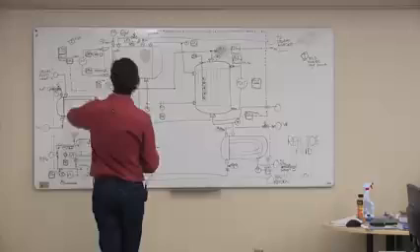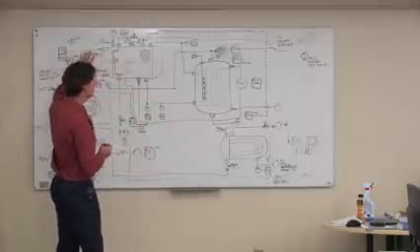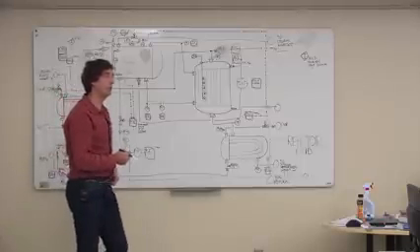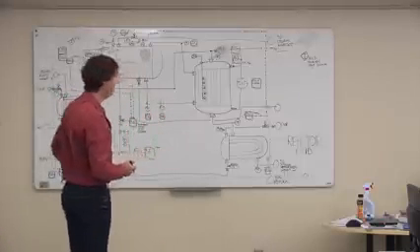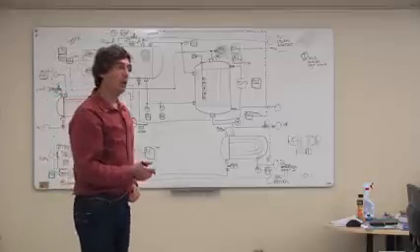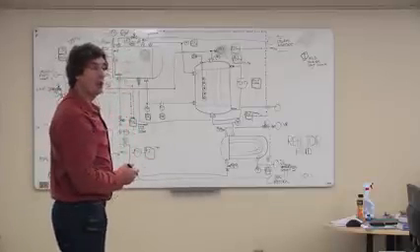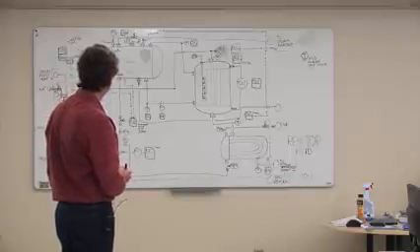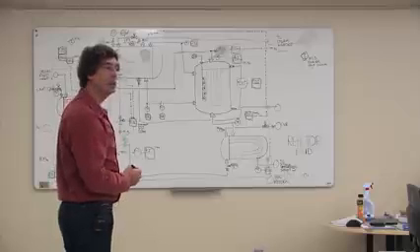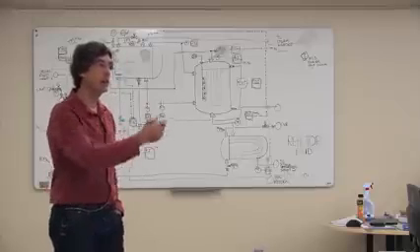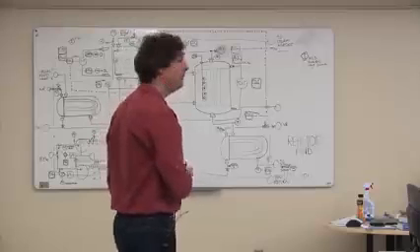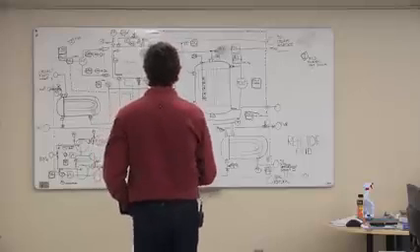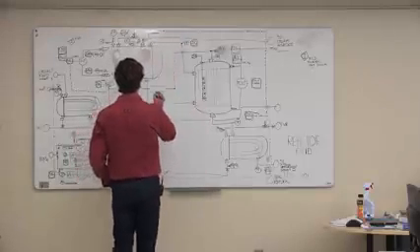Just a basic level gauge. Well, the level's here, right? So yeah, you could drain a little bit off, except that the level would probably refill as fast as you can drain it out of there. Can we not see it through the glass? You see the solids, you mean, or see the level? You might see the solids. I doubt you'd see the solids because you really don't want to have that many solids in there. You could be measuring conductivity, yeah, because the conductivity will go up as you have dissolved solids. So we could put an analyzer in there on conductivity.